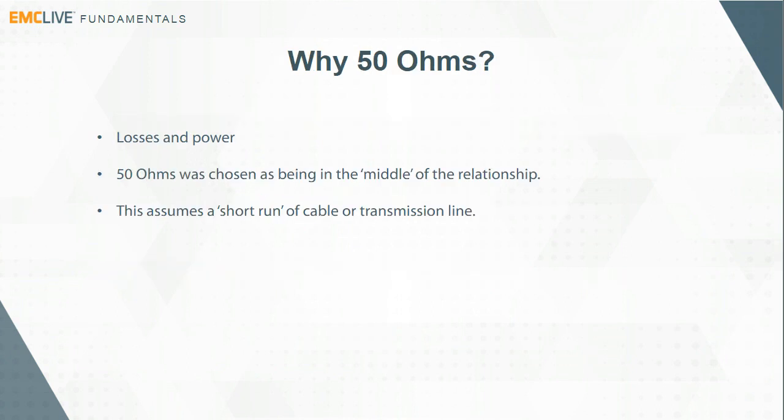You're probably asking, why do we use 50 ohms? You could be working in EMC for 20 years and not know why 50 ohms is kind of the golden impedance for our industry. What it comes down to is losses and power.